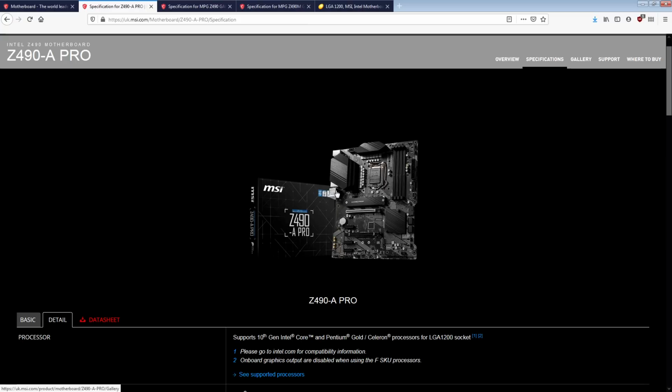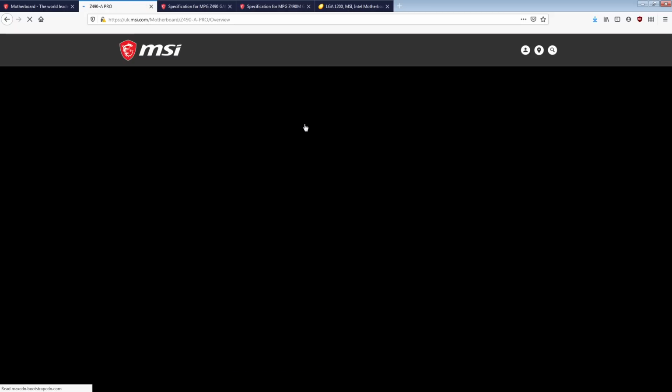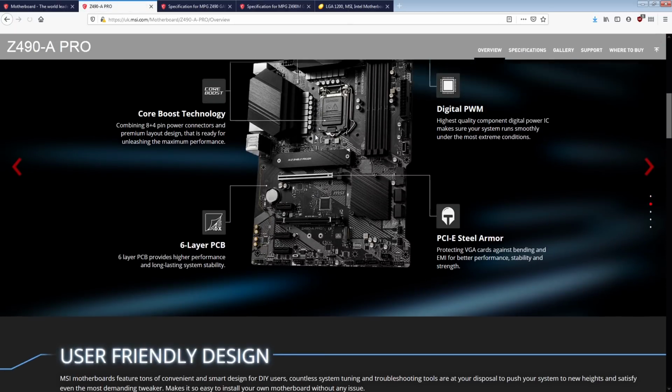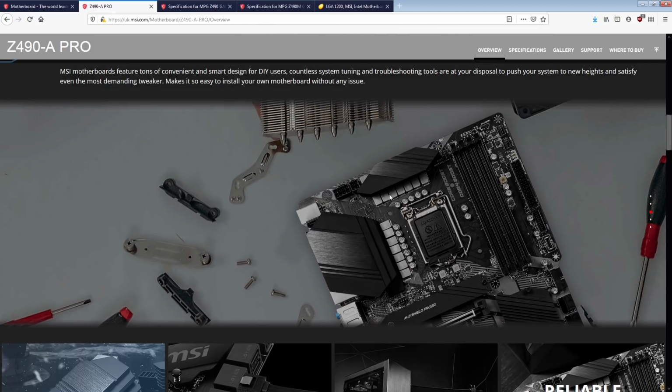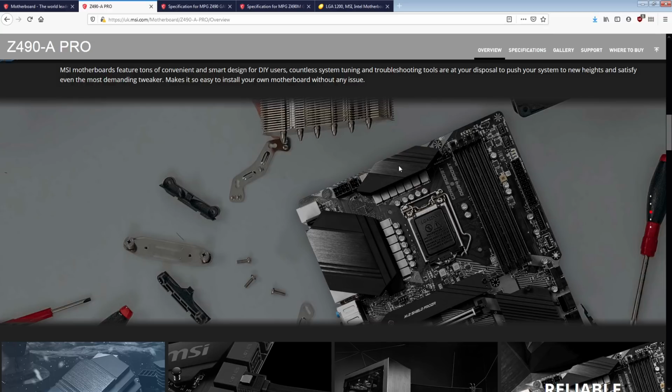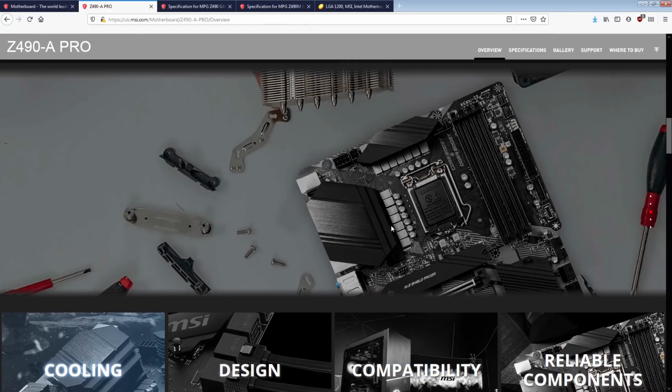Because the VRM itself is the same. So the biggest difference there is the heatsinks. And, well, let's see if they have a better picture of that heatsink. But that doesn't look that bad. And also, you have to consider they don't have all six of the phases under one of the heatsinks. I think it works out. It looks like they have 3. So actually, if anything, the part of the VRM that's going to run the hottest is the top part, with the smaller heatsink, because they've really split it half-half.